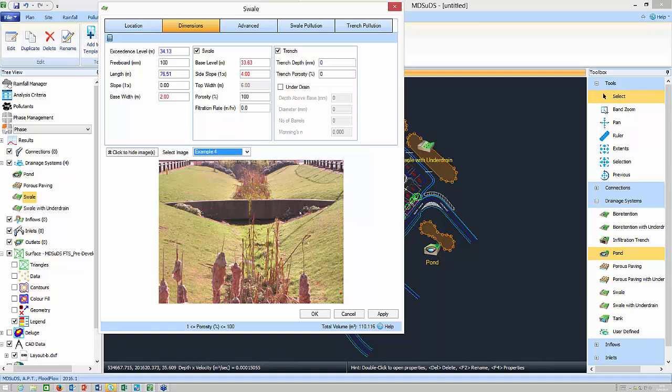And then there's the example from the Upton site in Northamptonshire, where we have these check dams to hold back the volume for the extreme events. So the regular events are conveyed through at the low level. Here are the naturalized bulrushes, and then you have a little slot here to maybe hold back for the 30-year return period or the 100-year return period when it weirs over the top.